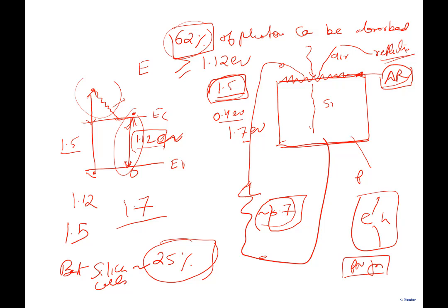And once we use a p-n junction, it can only result in a voltage of around 0.7 at the most. So the desire to separate electron-hole pairs leads to a p-n junction, which leads to 0.7 volt in the external circuit. All that extra photon energy, all you're left with is 0.7 volt here. All right, so let's come to the p-n junction.